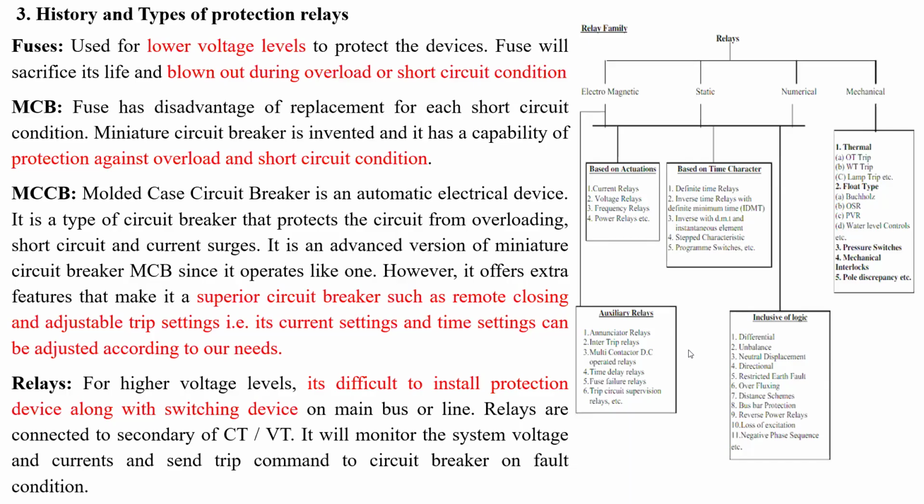Then they invented the molded case circuit breaker. It is an automatic electrical device, a type of circuit breaker that protects the circuit from overloading, short circuit, and current surges. It is an advanced version of the MCB since it operates like one. However, it offers extra features that make it a superior circuit breaker, such as remote closing and adjustable trip settings.